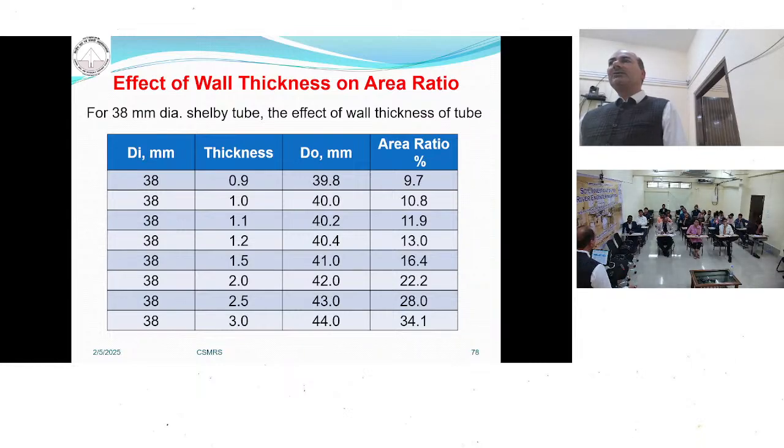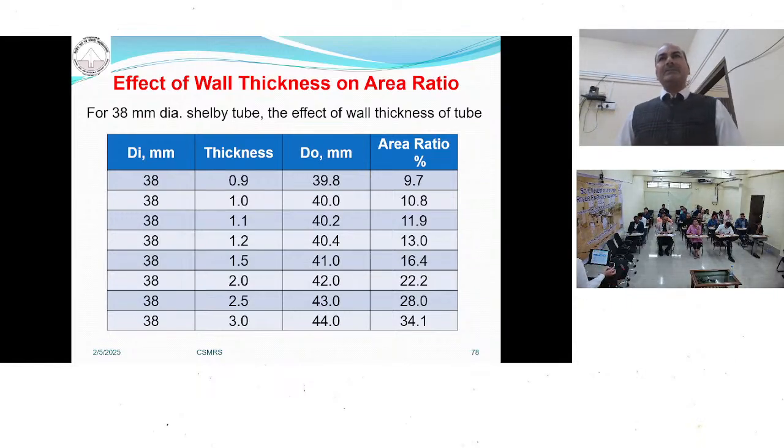Suppose your results come from a disturbed sample. While the designers are designing with those parameters, the cost will be very high. So in the case of a water resource project, sample collection is the most important thing. If your sample is contaminated, your result will be contaminated, and your design will be either highly under-designed or over-designed, and it will affect the cost many times.